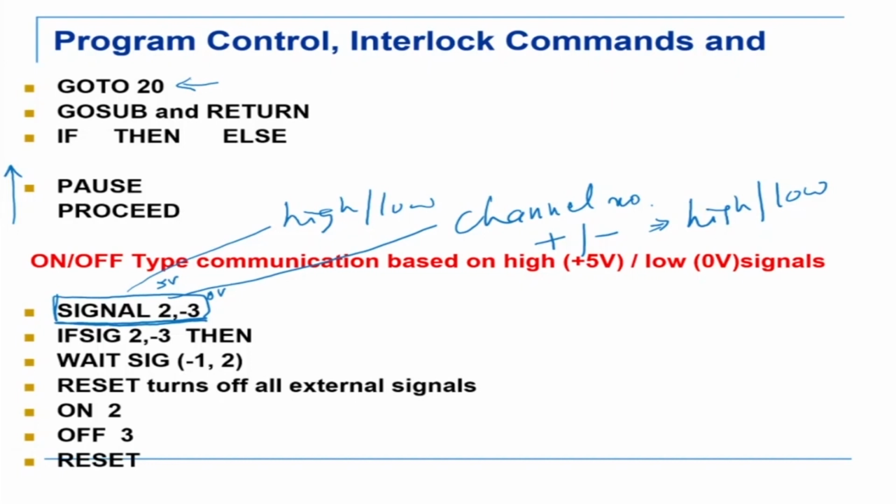and keep it in some index position. So one bad way of writing a program is that you can repeat the number of lines over and over again. For example, move P1, then open, then move P2, and then close, then depart. So you do that. If you have to pick up 1,000 times, you write that 1,000 times. That's a very bad way of writing a program. Now, a good way of writing a program would be if you can write a subprogram for repetitive tasks. So whenever it has to pick, it can go to that subprogram and pick. Or if it has to index, it can go to the subprogram and index.